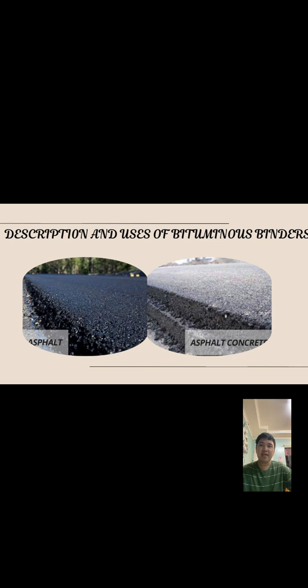More recently, viscosity grading has become the preferred method for classifying asphalt cements, as it provides a clearer measure of the material's consistency at different temperatures. For the applications of asphalt cements, they are primarily used to produce hot mix, hot laid asphalt concrete, and this type of concrete is widely utilized for constructing highways, airport pavement surfaces and bases, parking lots, and industrial floors. The specific grade of asphalt cement determines its suitability for various applications, ensuring optimal performance in each use case.